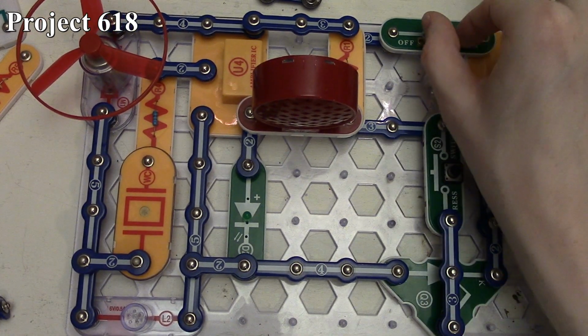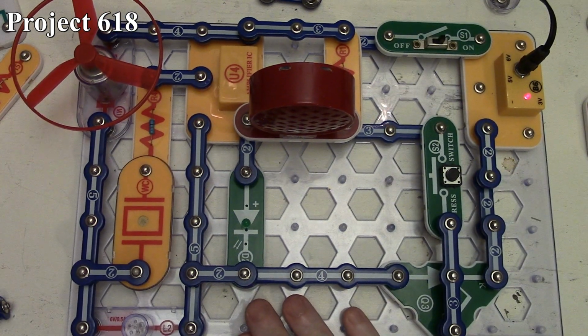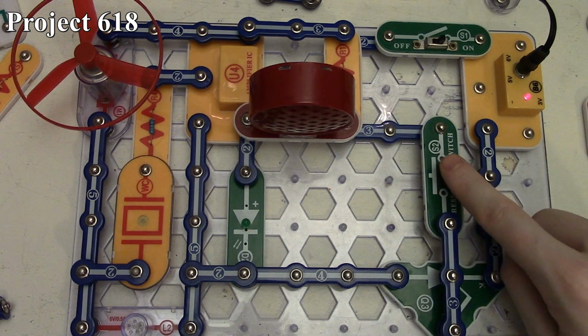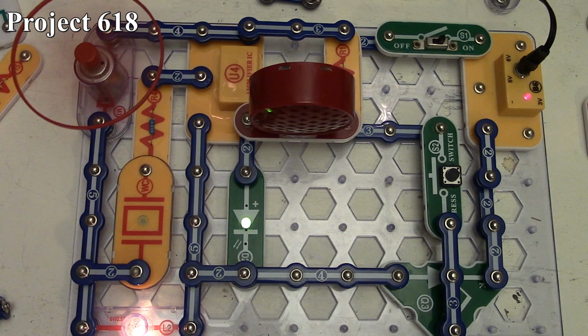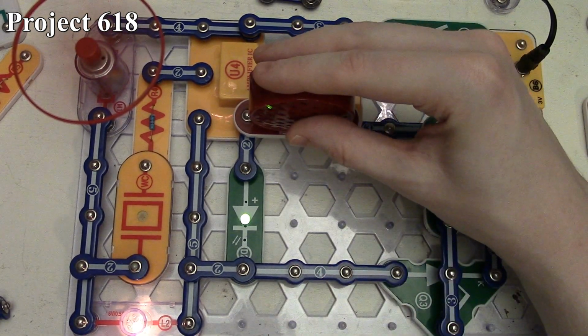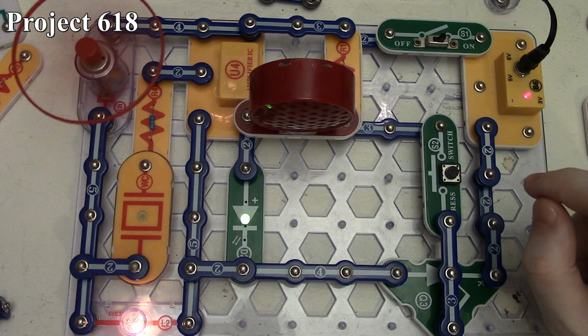So when we turn on the power, nothing on the circuit happens because the SCR gate has not been triggered on there to allow current to flow. When we press the press switch, it gives a small boost of current to the gate that turns the SCR on and now allows current to flow through our circuit. And because of that, our motor spins up, our 6-volt lamp glows, we can hear the motor through our speaker, and our little green LED lights up.